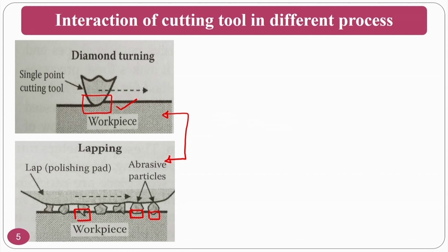For that purpose, what will be the solution? In this particular thing, we do not want feed marks, even though we are getting a very good surface roughness and figure in terms of diamond turning as well as lapping. But the problem in these conditions is that you are going to get physical feed marks, which are nothing but scratches or lines on the lenses.